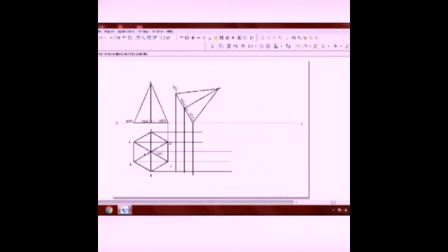Now, the lines, as I've already mentioned, are to be construction lines. Therefore, you have to select these lines and make the thickness 0.13. Anyway, these lines are to be thin. Unfortunately, we are drawing them thick. You can draw them thin and make them thick, or once and for all, you can draw thick lines. Now you select it.